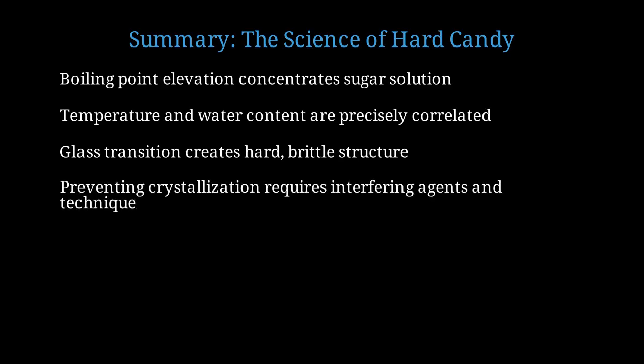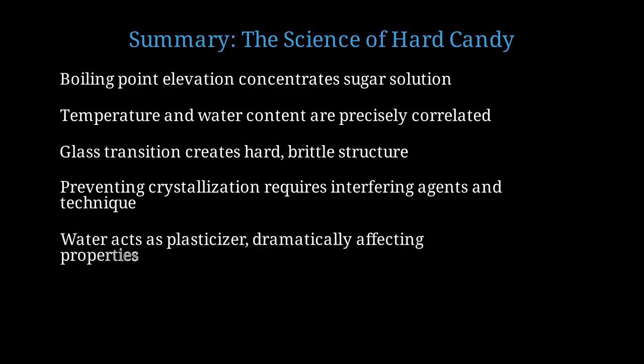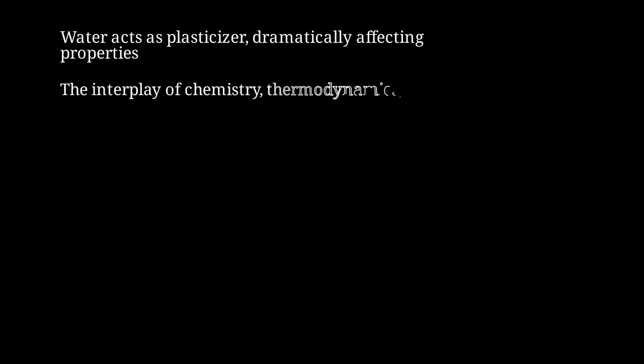Preventing crystallization requires both chemical interfering agents and proper technique to avoid nucleation. Water acts as a plasticizer, dramatically lowering T sub G and changing mechanical properties even in small quantities. The entire process beautifully illustrates the interplay of solution chemistry, thermodynamics, kinetics, and material science.